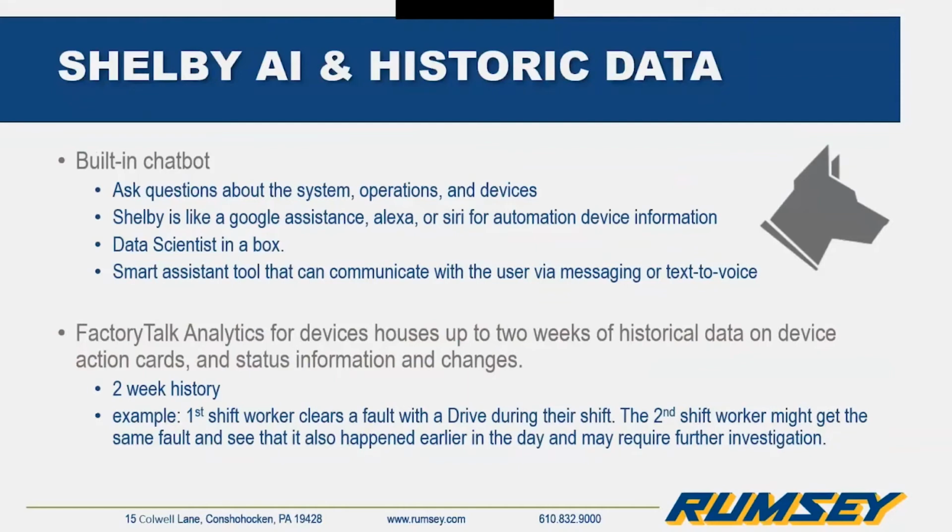I have a little example here where a first shift worker clears a fault on a drive during their shift, and then the second shift worker might get that same fault and see that it happened earlier in the day, and that drive might require some further investigation. So just a really quick example of how the historical data can be used to correlate things, again with all the information that it provides.